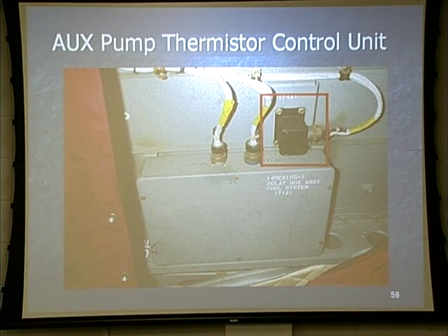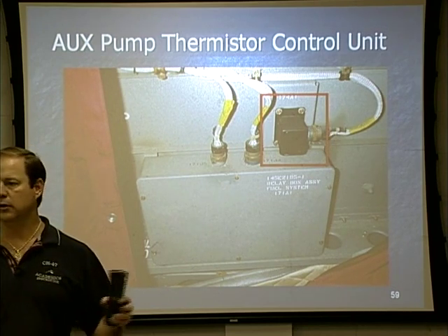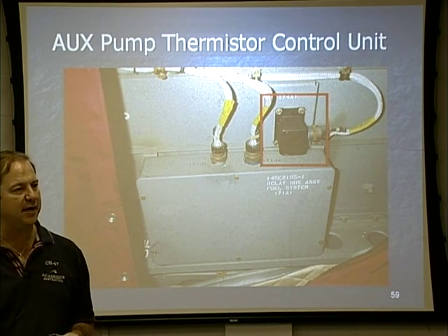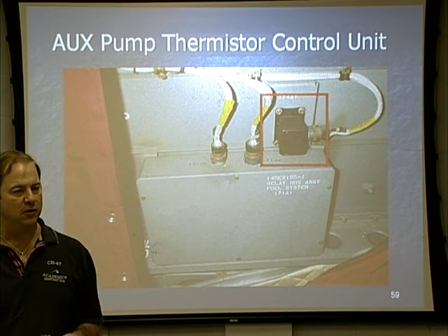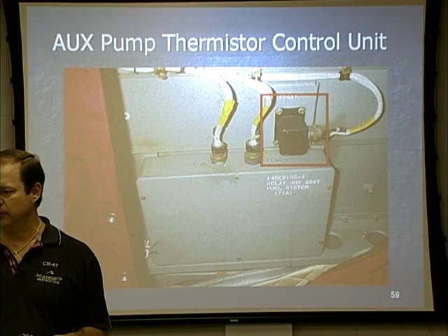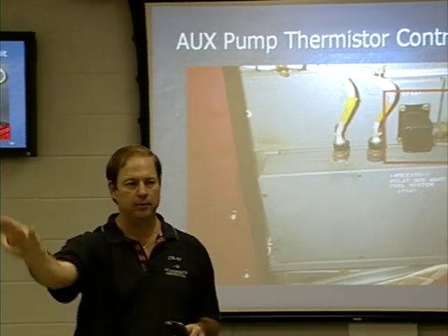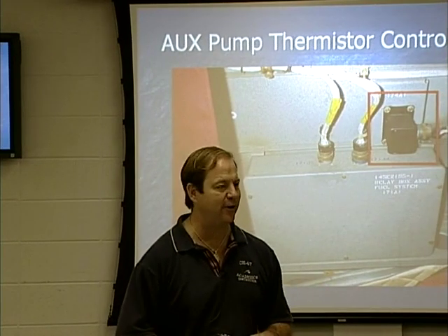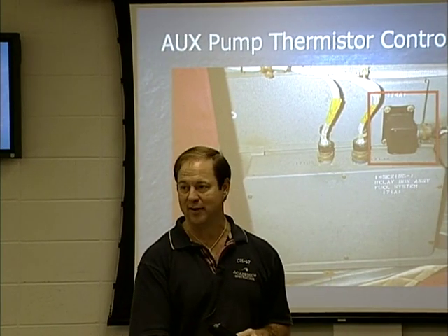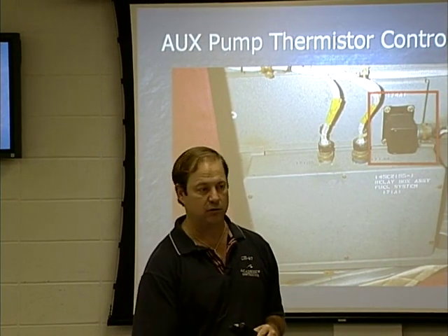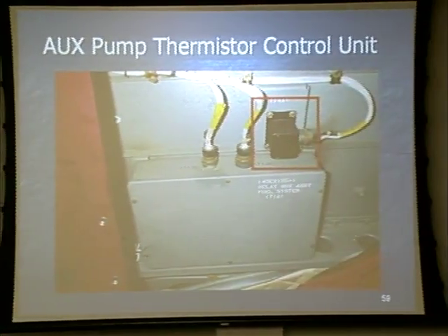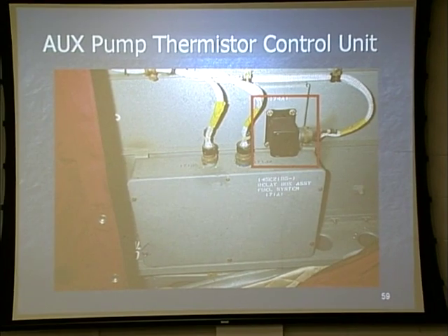Do we sometimes decide, man, we got to pick up a real heavy load, we're only going to top off the main tanks? But sometimes we get in the habit of doing what? All fuel tanks on, crossfeed open, or crossfeed closed. Boom, boom, boom, boom. Oh, those tanks were empty. Guess what? You're still not going to hurt anything. Why? Because the system's protected by these thermistors. We'll actually talk more about them here in just a second. But there's the thermistor control unit on the top of that relay box.